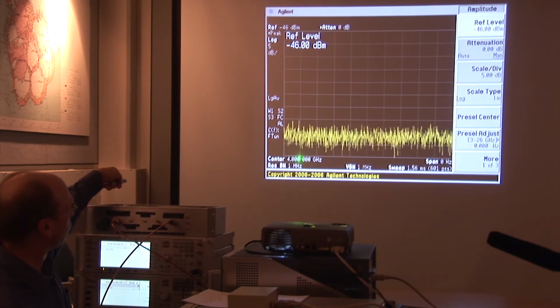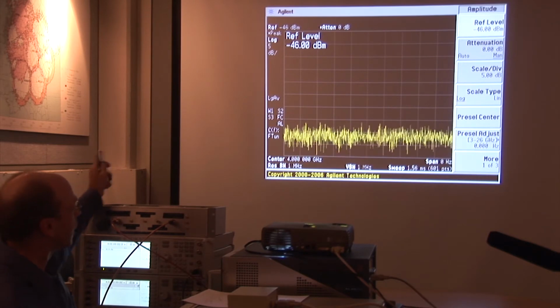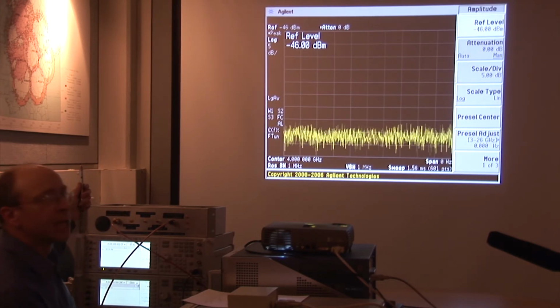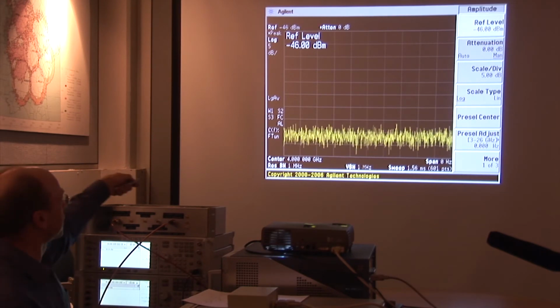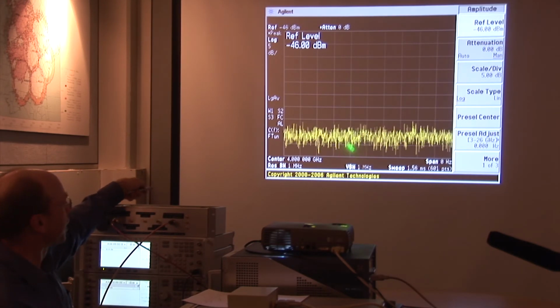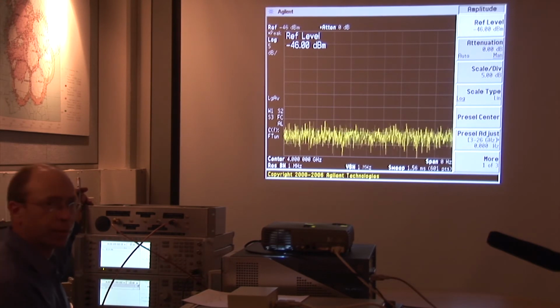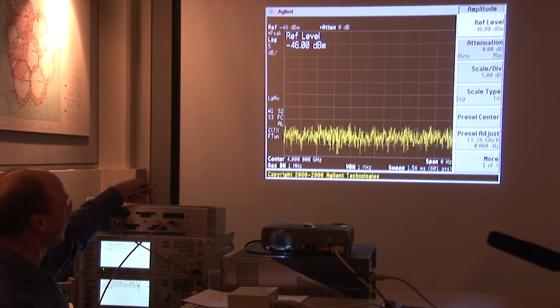And we are tuned to 4 gigahertz, which is the RF frequency. On a typical earth station or digital point-to-point microwave link, we would actually be tuned down to the IF frequency, but it would still look like this. It would have just gone through a mixer and therefore would be running down at 21.4 megahertz or something like that. But you'd see the same kind of display.